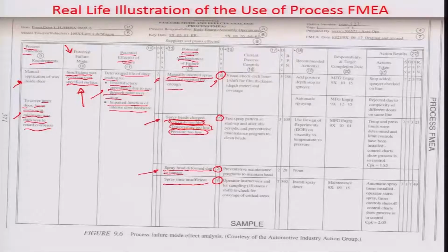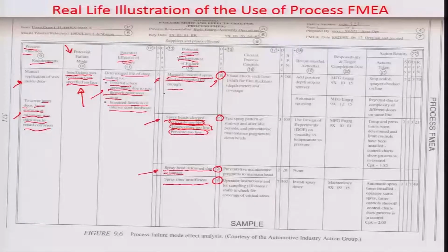So therefore, what he has done is a sort of a defect tree analysis, where because of this failure mode, whatever are the reasons associated with the failure mode are rated in terms of how much they contribute to the failure mode, in terms of their occurrences, etc. So once this is classified, then he looks at whether, if these are the various mechanisms of failure, there are any checkpoints to see whether these failures through these different reasons are being monitored and controlled.